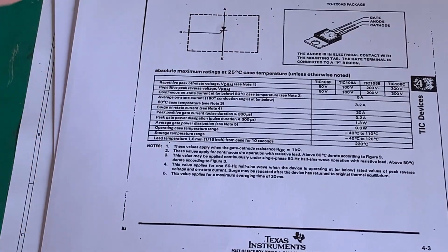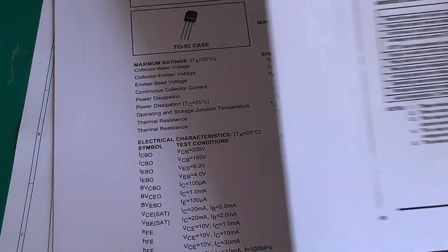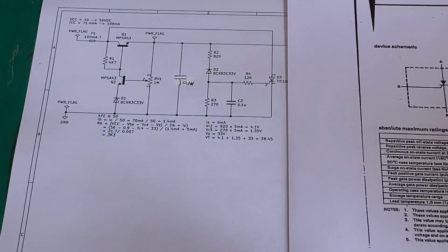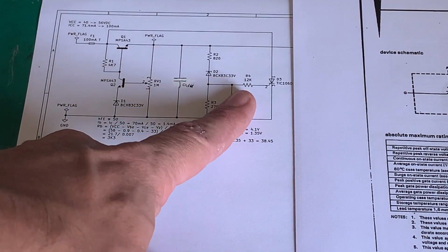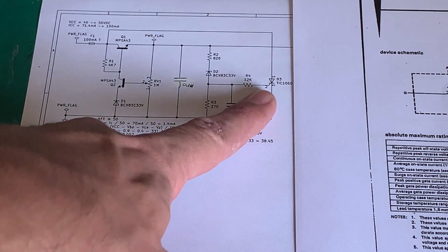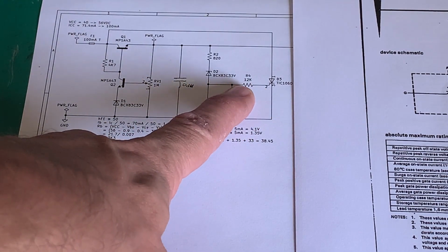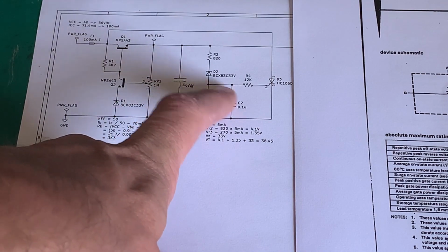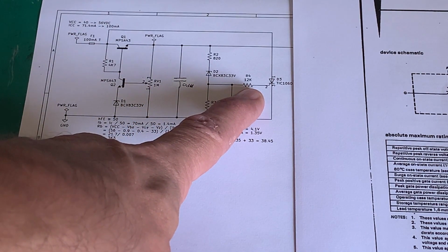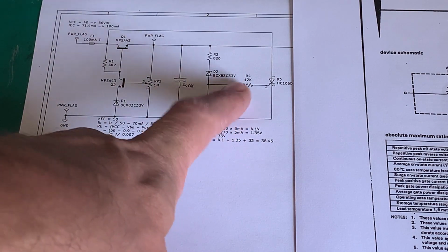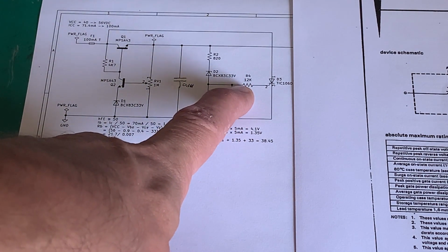If we go back to our circuit, I'm just going to move this across because we don't care about that part of it. You'll see we've got a 12K resistor on the gate, and that is to give us, from here, that 0.6 volts at 60 microamp, I think it was. So that's what that current limiting resistor is there for.